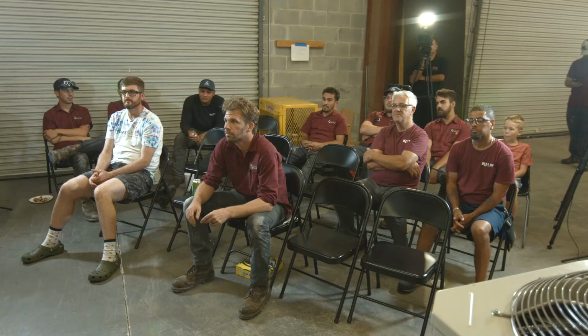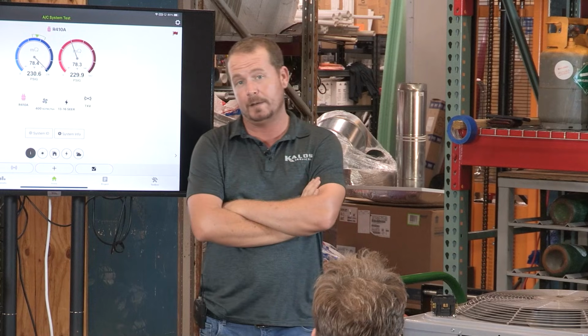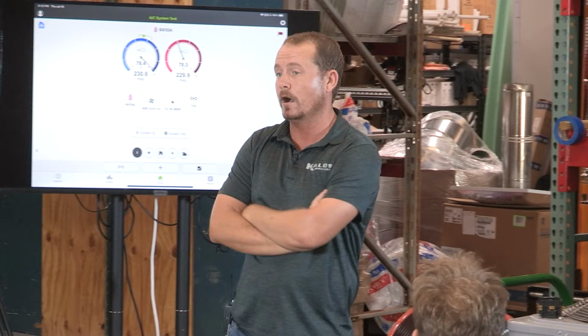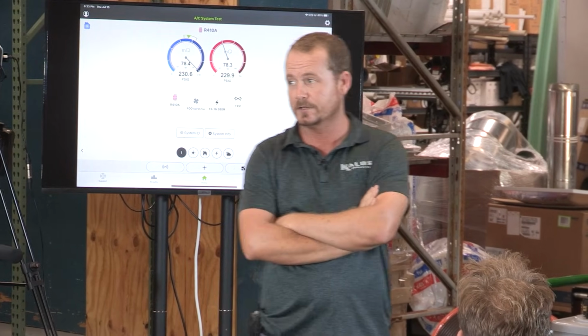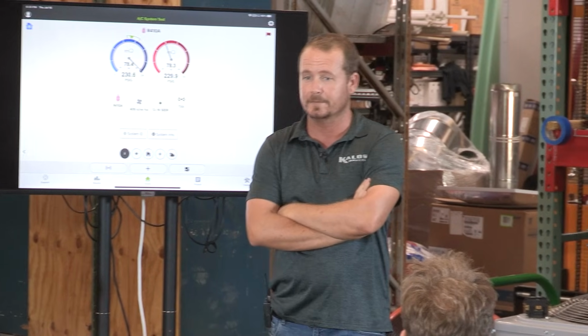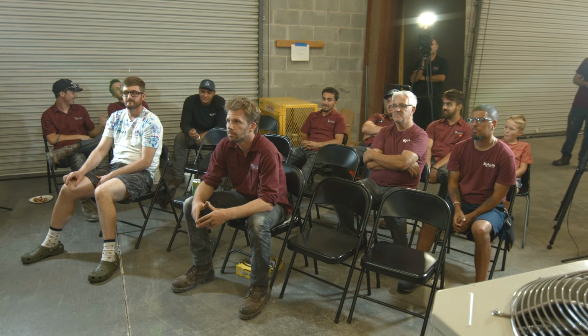What else? Frozen evaporator coil. Yeah, that definitely is going to cause low system airflow. Now, often it's low system airflow that caused the coil to freeze up in the first place, but it could be something else. Could be a bad TXV. You forget to cut the return?